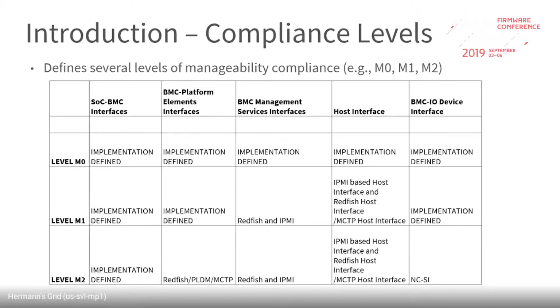For the BMC to platform elements, basically the different sensors on the board connected to this SOC, we plan to use Redfish, PLDM, MCTP. And for the BMC management services interface, it's the same as level M1, which is Redfish as well as IPMI. Host interface is the same as level M1. And for BMC to IO device, we plan to follow the NCSI specification, which is based off of the DMTF forum.